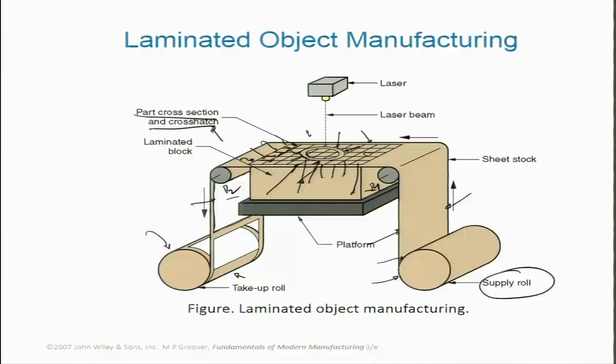We were talking about different rapid prototyping strategies. The first classification was based on what material you were starting with. In the context of solid based materials, we were talking further about laminated object manufacturing, popularly known as LOM, where I described how a laser cuts the sheet of plastic or paper, whatever is used, segment by segment into different zones. One zone is where the actual part segment remains, and the other is where the cross hatch portion remains, which can be removed later as the part needs to be released.